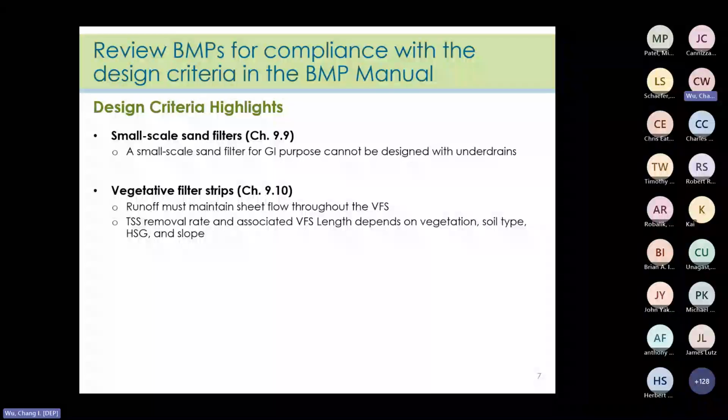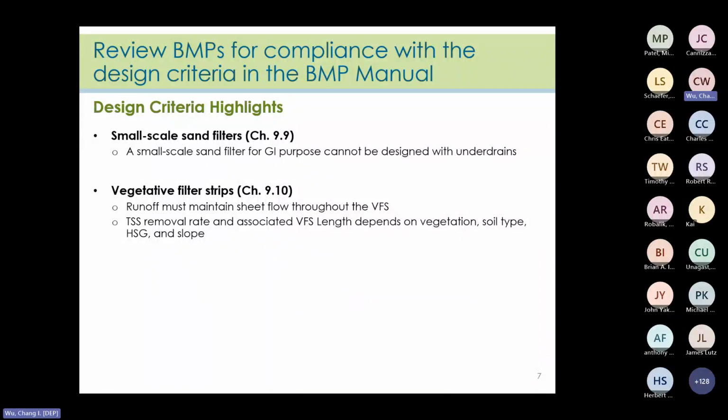The next one is the small scale sand filter. A small scale sand filter for GI purposes cannot be designed with an underdrain. So it has to be designed to infiltrate the runoff into the subsoil.